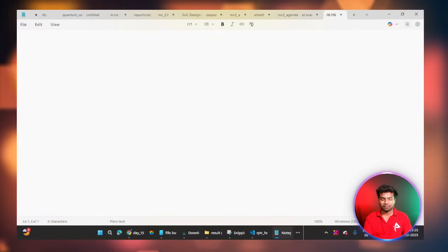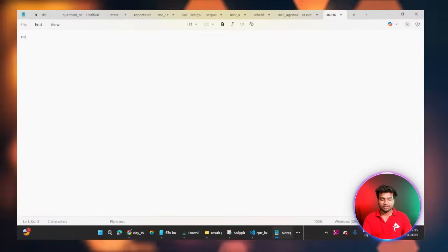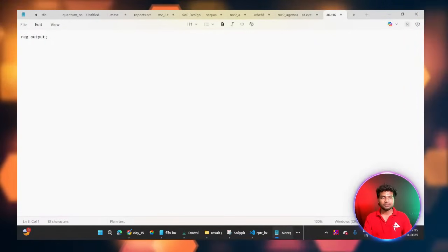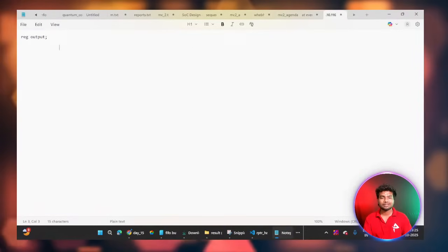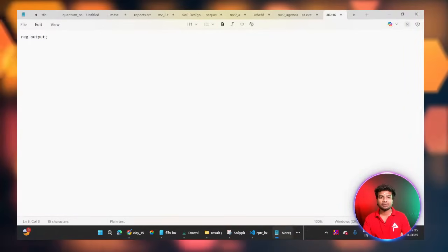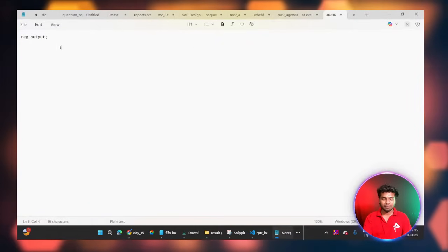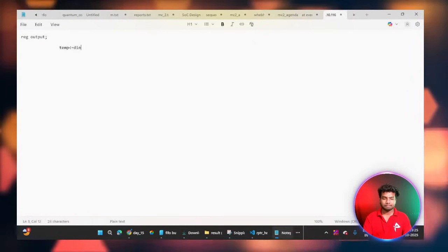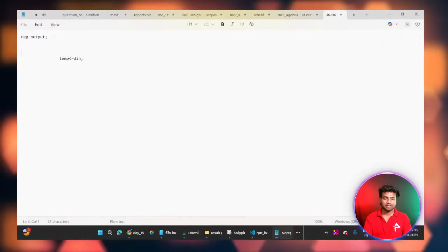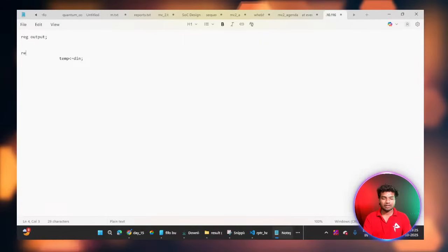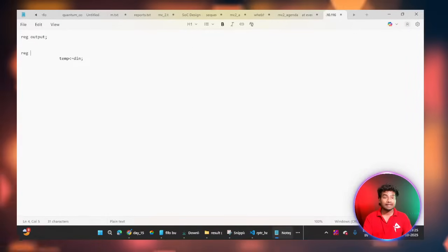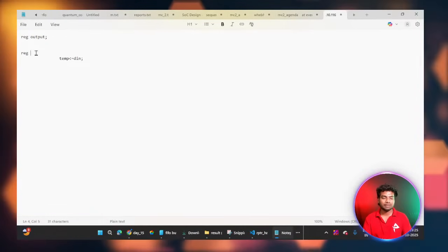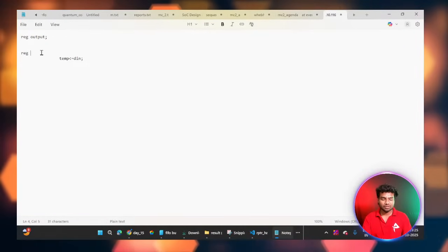So firstly I have the signals like a reg output. This is my output signal. To use double synchronization, you have to use a double register. So firstly I am using one temp here. This is my data in. I am using another register; the temp is my internal register. This reg output is my port list output signal, and temp is my internal register, so an internal signal.